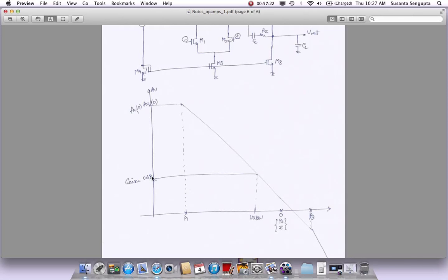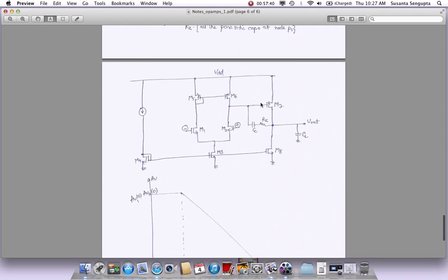So for all these frequencies where it matters that it could actually start oscillating or could go unstable, we are ensuring that the phase never actually crosses 360 degrees. Our phase margin is at least 70 degree, 60 degree, or even up to 90 degree. That's great to have those numbers, and that is how we have now gone through this whole exercise of designing it.